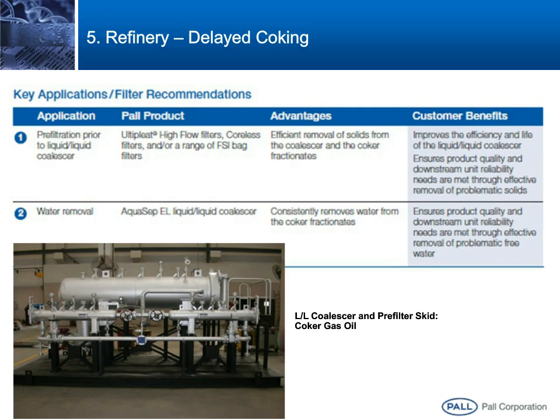So the Aquacep EL liquid-liquid coalescer would be the product of choice here, well suited to the relatively dirty environment on many of these streams because of the presence of the coke fines. But what you will be seeing is ensured product quality downstream, whether you're going into blending or whether you're feeding other unit operations. Here we can see on the bottom of the sketch an example of a unit on a coker gas oil stream, a horizontal liquid-liquid coalescer.